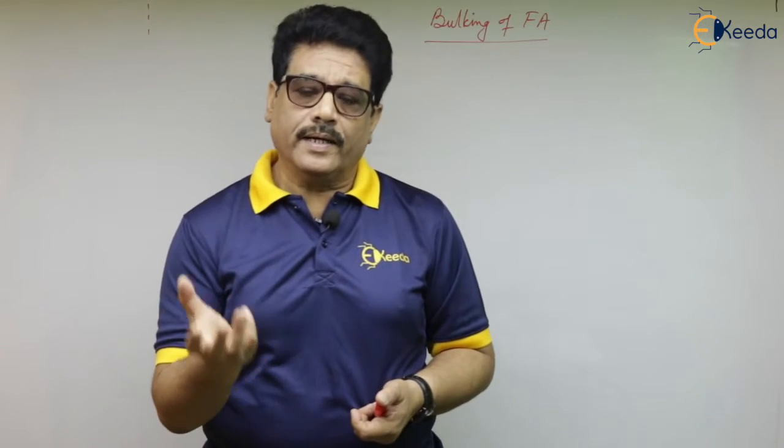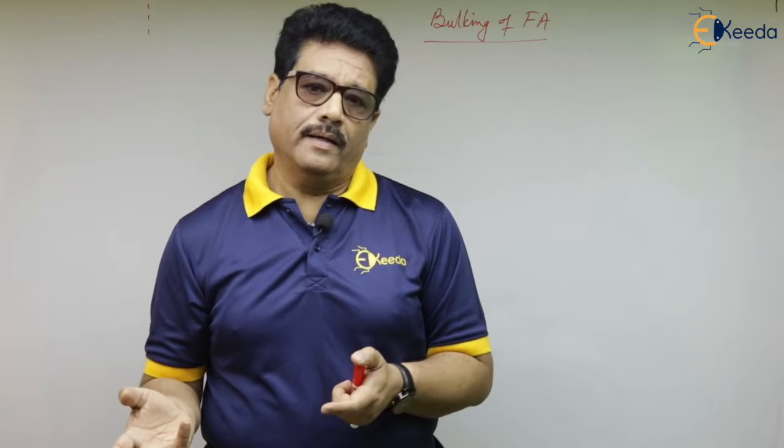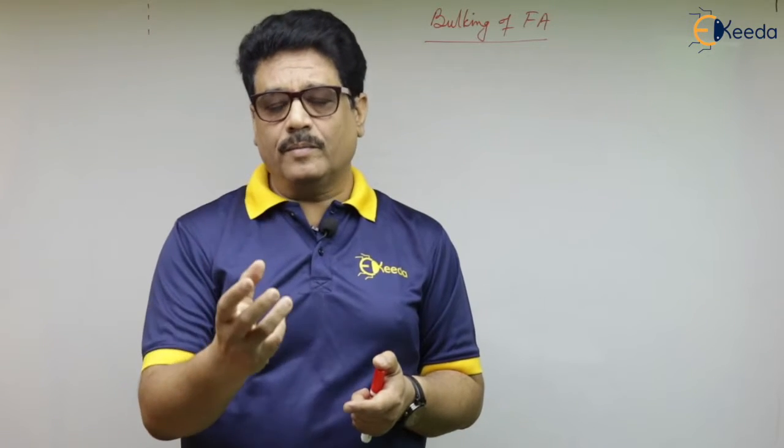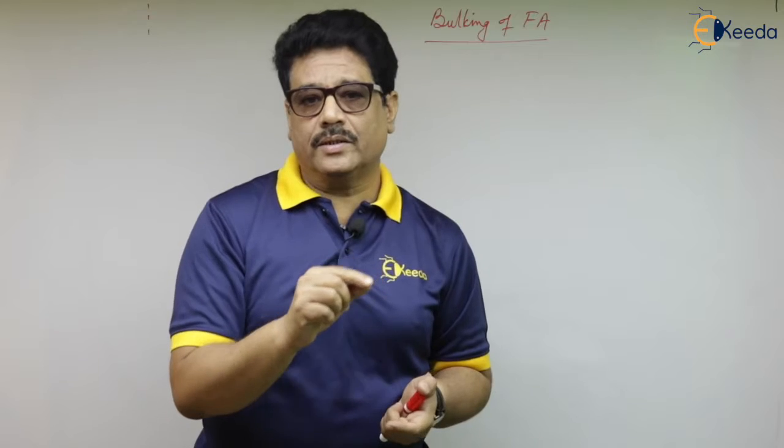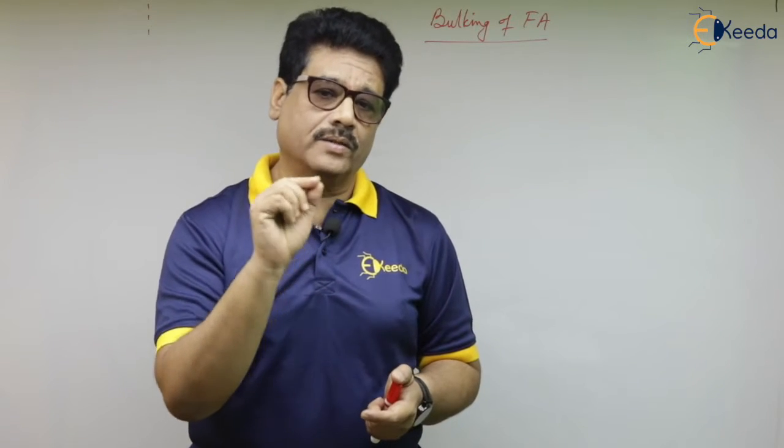But in case of the presence of moisture, I am always on the losing side. I will get less sand in terms of kgs. This is the effect of bulking. So the engineer in charge should be very well versed with the bulking of sand.